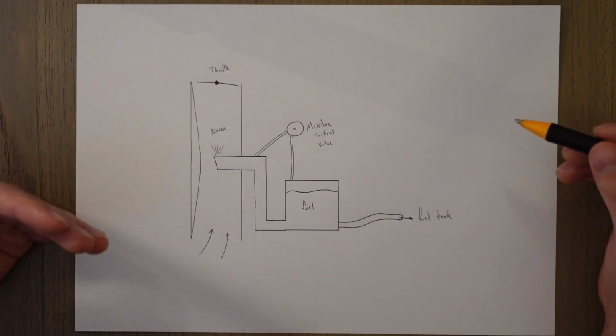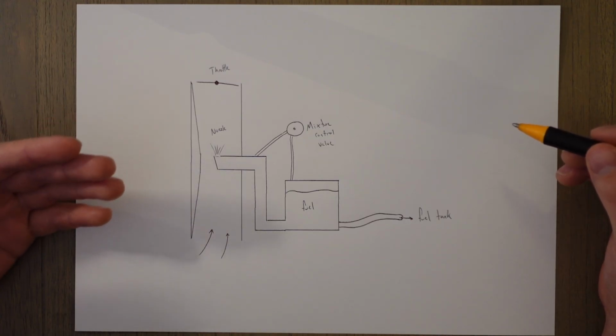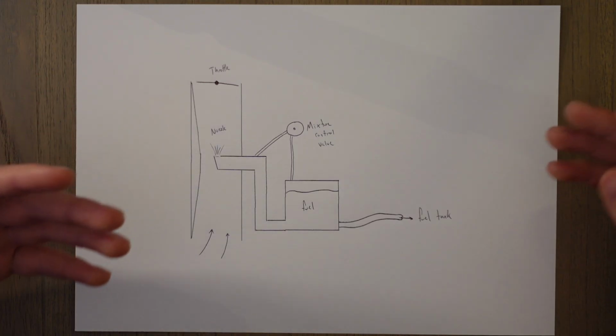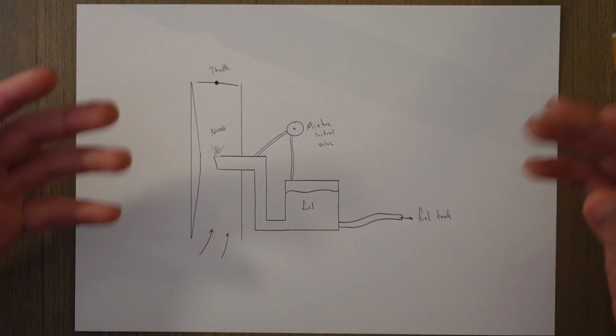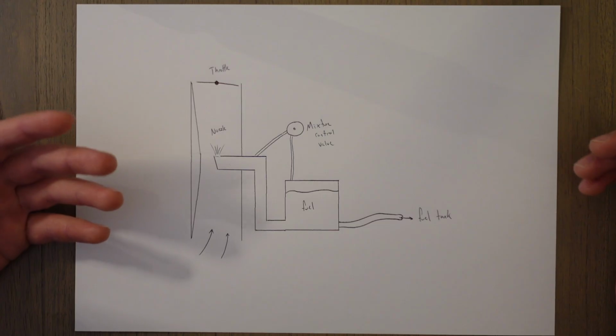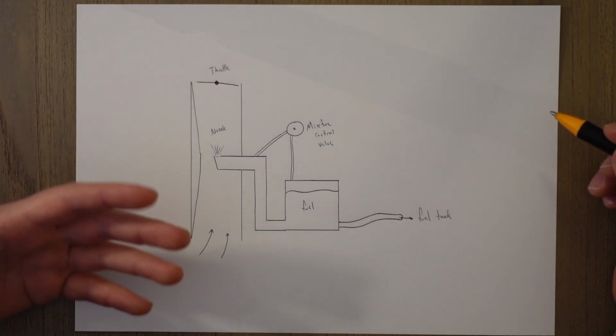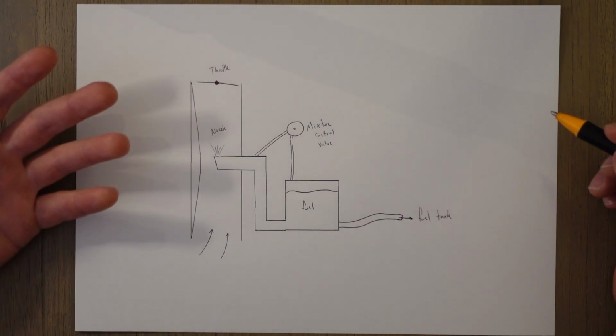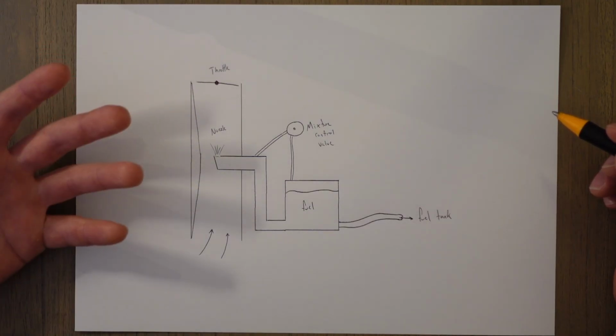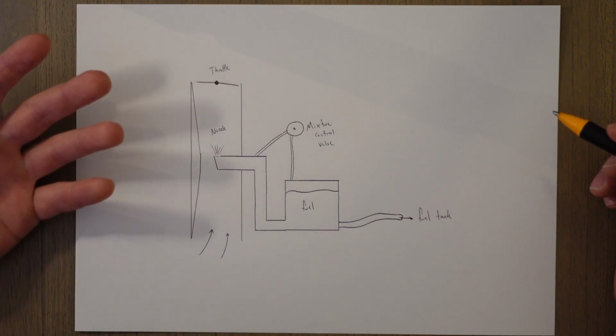This is very useful at high power settings like at takeoff, because you don't want to risk having detonation, unstable engine characteristics at this point in flight. So you might increase the richness by about 30% compared to the normal ratio. This has the disadvantage of burning more fuel though.